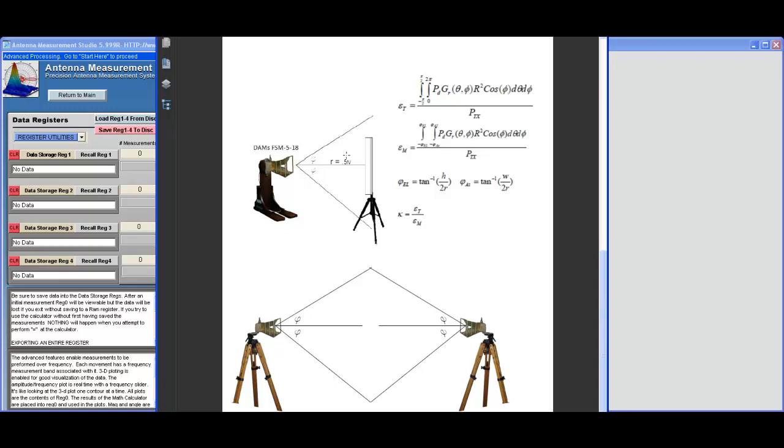The overshoot of the main beam is corrected by measuring the efficiency, and measuring the efficiency over the extents of just the mirror. Those two efficiencies as a ratio form a correction factor. The overshoot is naturally a function of the distance from the mirror and the height and width of the mirror. The Diamond Engineering standard mirror is 24 inches square, or approximately 0.6 meters.